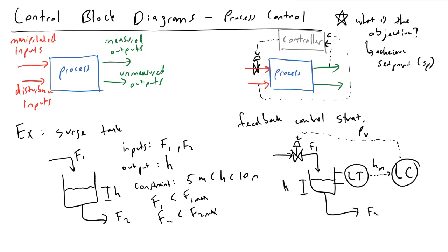And if you wanted to have more to this story, why aren't we manipulating F2, even though F2 is an input? So in the case of F2, the issue here is that F2 can be a controlled variable in a downstream process, and if it is, then we have no control over that. So we're going to essentially let F2 be its own thing, and we can't account for it in our controller.